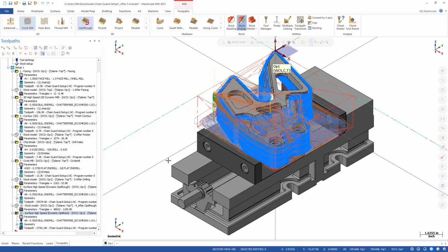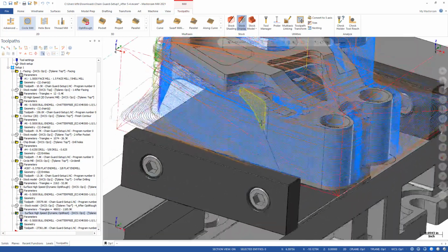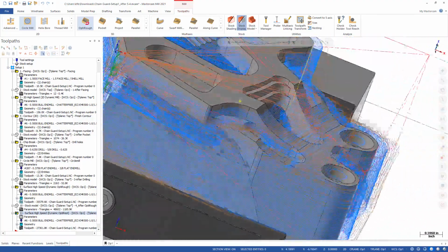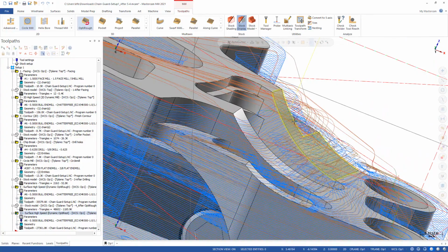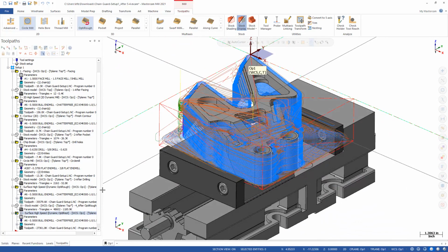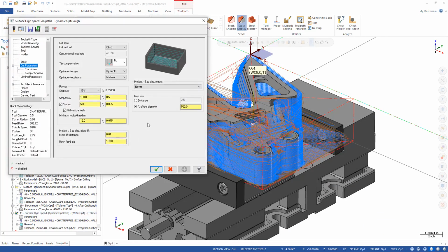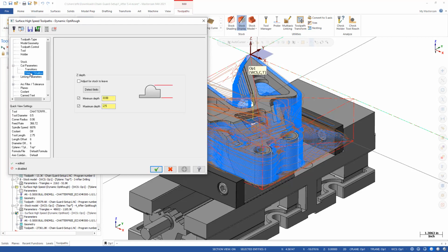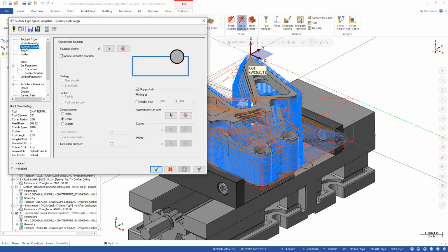Now that this toolpath is created, we'll take a look at it. As you can see, we're still machining the walls, the vertical walls, but we have some more additional passes in the sloped area as well. We could go back in and adjust some of these parameters a little bit. We're not going to do so now, but of course we could change some things like the transitions or fine-tune the steep and shallow areas. More importantly, we could work with the toolpath control and have it look at other options besides skipping the pockets or how you compensate to.